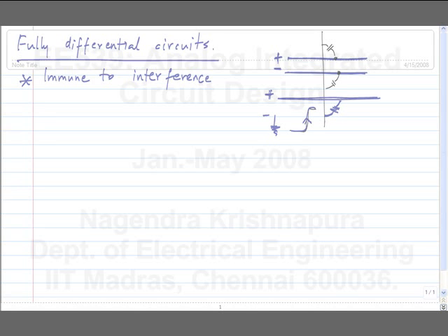It also causes less interference, okay. So, now let us say we consider our signal as the interfering signal. It will also interfere with other signals. So, let us say we have a single-ended signal. Then if there is a voltage change on this wire, it is also impressed on the black wire, okay. Whereas now, if there is a signal between these two, that is a differential signal, what happens? Both of them couple to the black wire. So, what will be the net result?